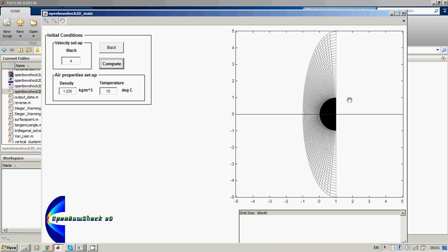I know for the circular cylinder the maximum Mach number you can make is 8. I know for more slender bodies like the logo body, the maximum Mach number was I think 10. And if it's a little bit more slender, but if it still has kind of circular shape, it can go until Mach number 20 or 15. I think I tested one geometry at Mach number 20 and it worked perfectly fine.